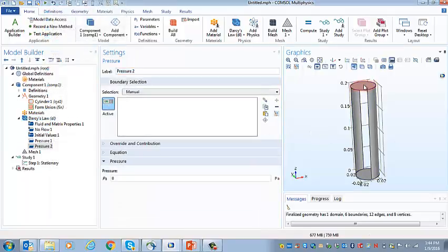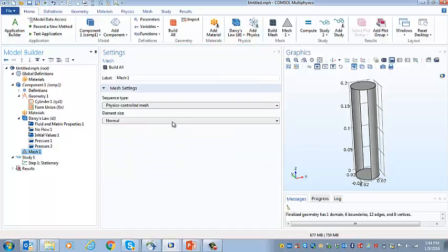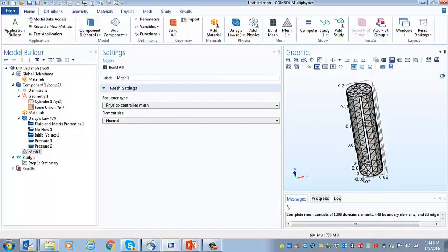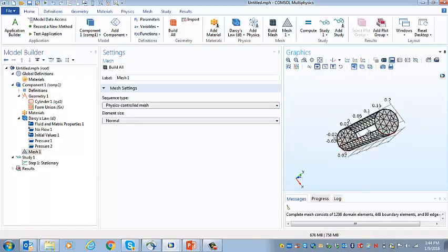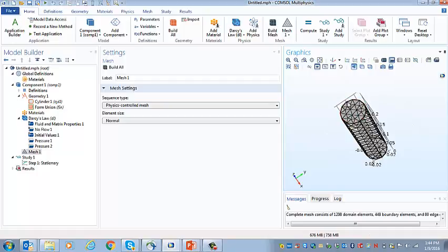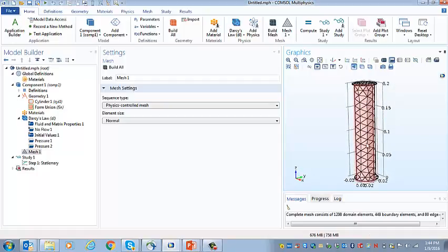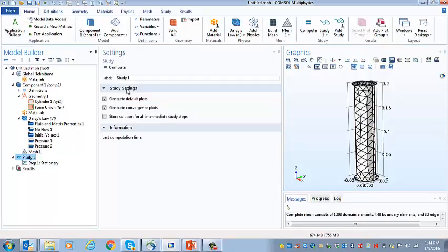At the top, I'm going to select the top there, and this boundary condition requires that the pressure is 0 at the top, and at the bottom we said it would be 2400 pascals, like so. And we need to have a mesh, so we'll take a look at the mesh. The mesh shows up on the sides of the model. We don't see the mesh internally in this view, but that gives us a feel for what the mesh looks like, the density of the elements in the mesh, and that'll be okay for our problem so far.